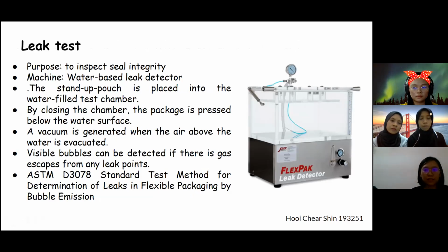There are two tests that can be conducted to test the stand-up pouch properties. The first test is the leak test. The purpose is to inspect the seal integrity. We have to make sure that the packaging is sealed properly, and to test the seal integrity, we can use a water-based leak detector. This is one of the leak detectors that is used in industry.